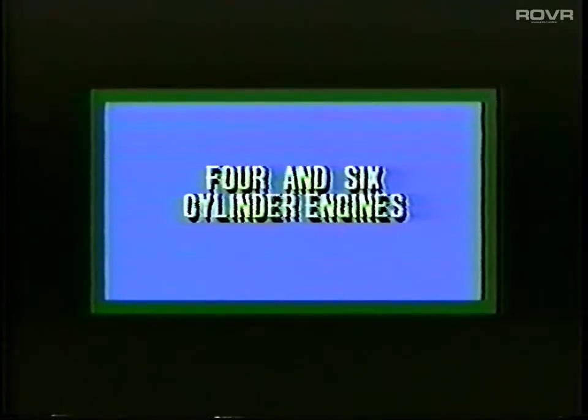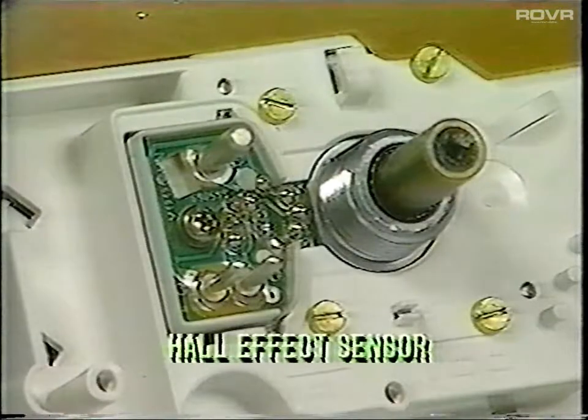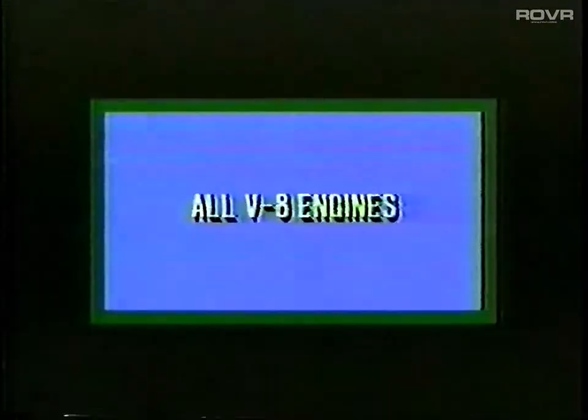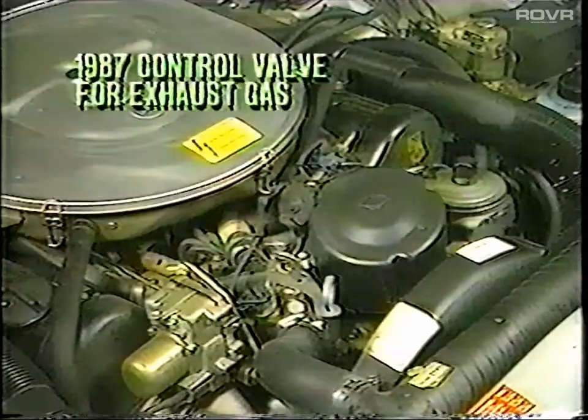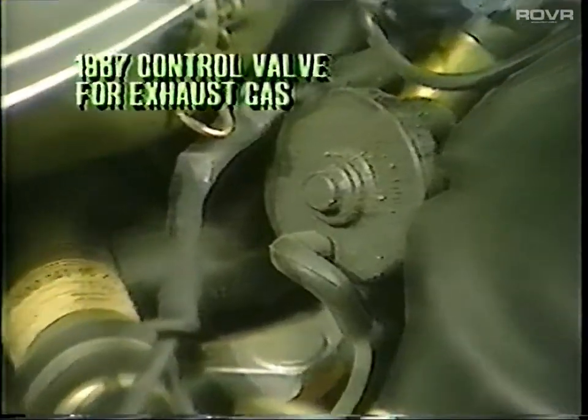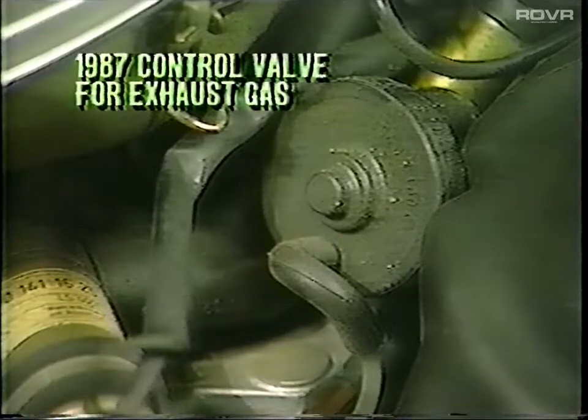Looking further, we find changes that relate to specific models only, such as the installation of the familiar Hall effect sensor on all 4 and 6-cylinder models. This now provides the speed input signal to the CIS control unit. The V8 engines incorporate certain changes, such as the elimination of the control valve for exhaust gas recirculation, shown here on a 1987 model.